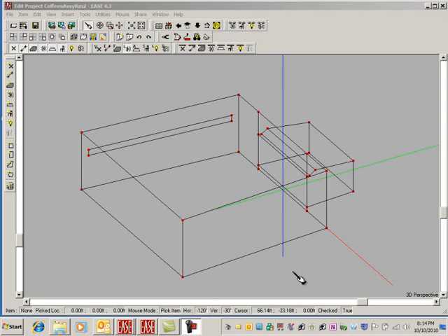Turns out that the first panel is 3.5 feet from this wall here, just like the window was, the glass. So we need to locate the first vertex. If I look in plan view, I can see that the suspended ceiling panels are 32 feet wide, and they're symmetrical about the y-axis, about x equals 0. On the minus side, the first vertex would be minus 32 and minus 3.5 feet.